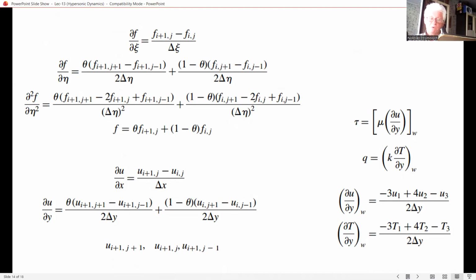Therefore, the transformation to zeta-eta space given in our two equations is still useful here, because the Lees-Dorodnitsyn transformation stretches the grid in the normal direction, especially near the wall, as I already mentioned. So it is frequently recommended to carry out finite difference calculations using the transformed zeta-eta space.